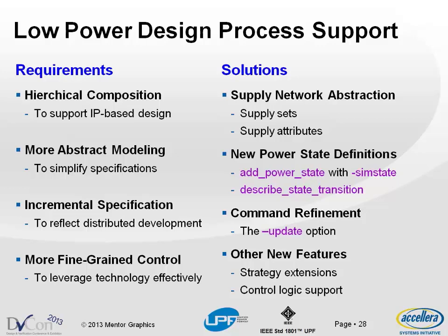We also need more fine-grained control. The concepts in UPF 1.0 were a little bit coarse, and in 2.0, there's been an attempt to refine them and make them higher fidelity with respect to what's actually going on in the hardware. So the approaches that have been developed in 2.0 to address these are, first of all, supply network abstraction. This is the concept of supply sets that I mentioned earlier, which I'll talk about in just a minute, and including the use of supply sets to specify the attributes of ports and IP blocks, especially hard macros in particular, to kind of round out and fill out the concept of the supplies that are used in the design.